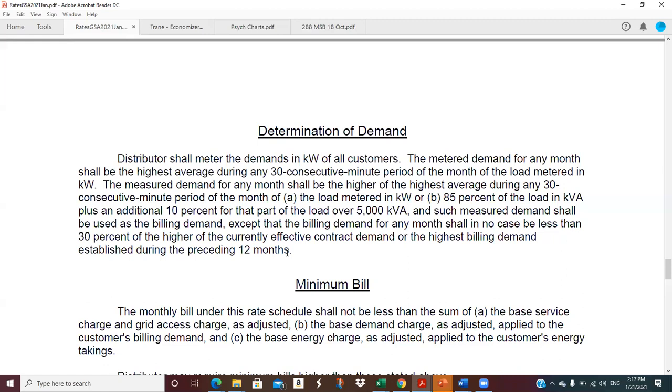There's one up in East Tennessee, and we get a year's worth of their utility data, and you started looking at their kW billing demand, and it was like 300, 300, 300, 300. And I'm sitting there going, now, look, these guys, they may be consistent, but they can't hit the same flipping number every month. And what it was is that was 30% of their contract demand.